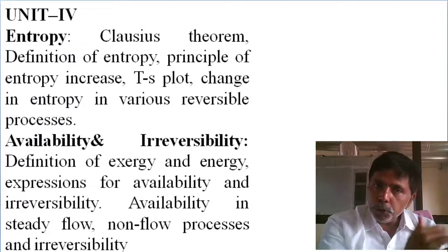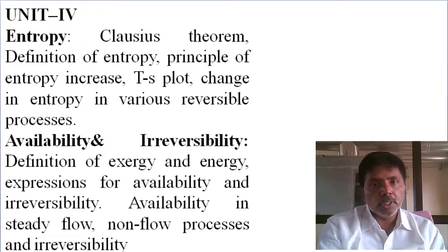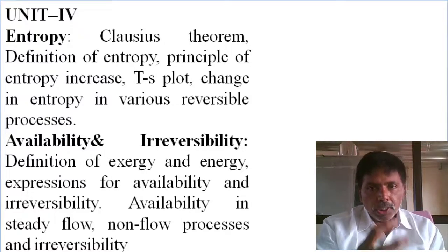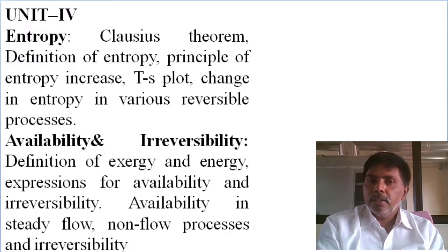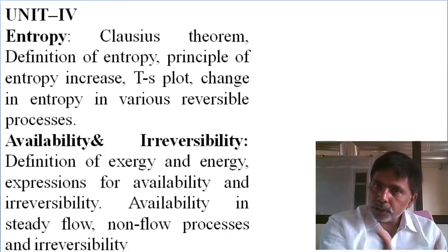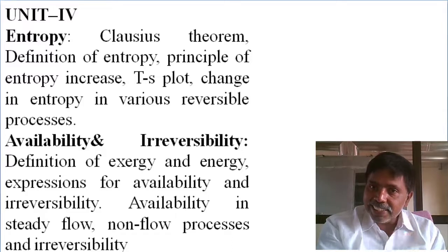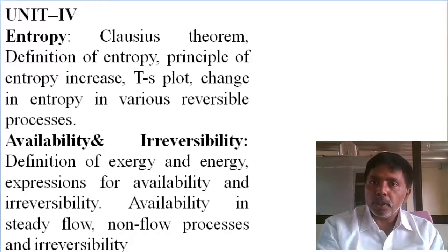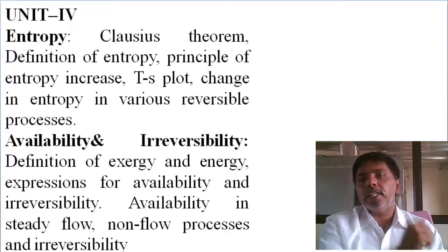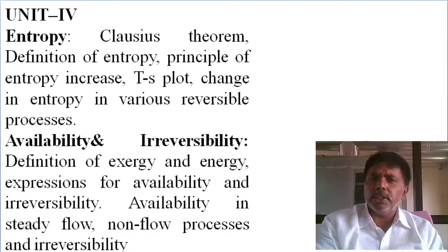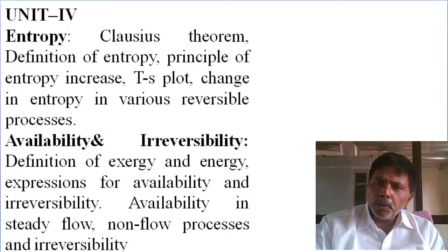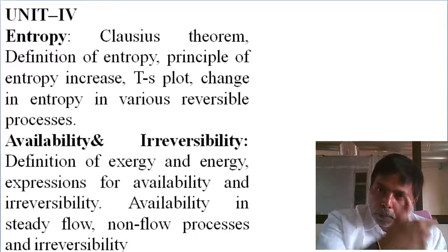Next, in unit 4 we are introducing entropy, because molecular disorderliness is the major driving force in determining the actual available energy. Energy means capacity to do work. Exergy means capability to do work. Now we require capability, not capacity. For each source of energy, you are able to determine the capability to do work.